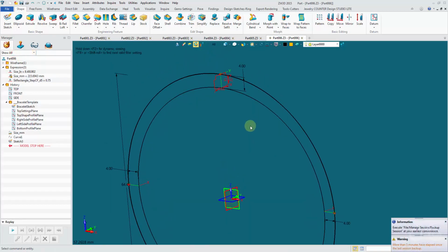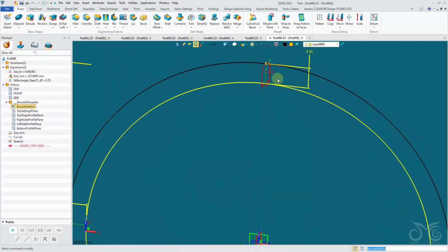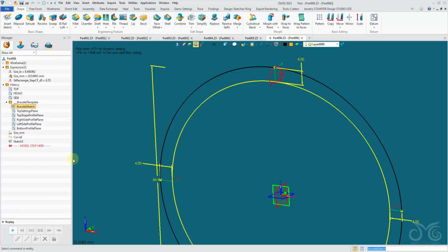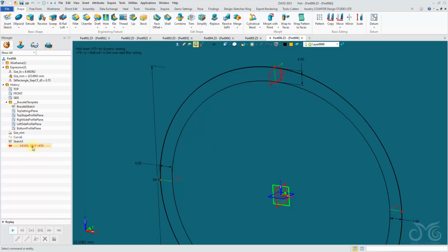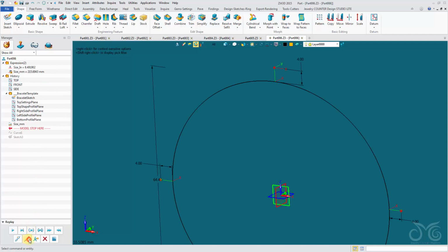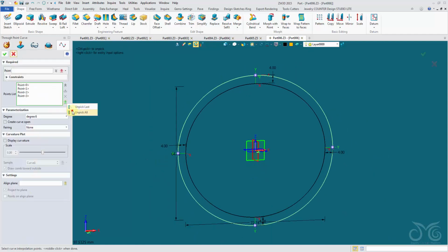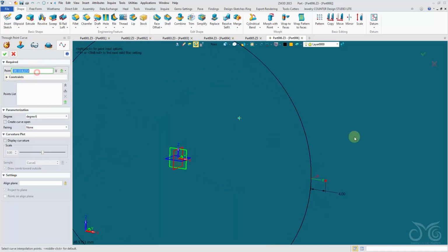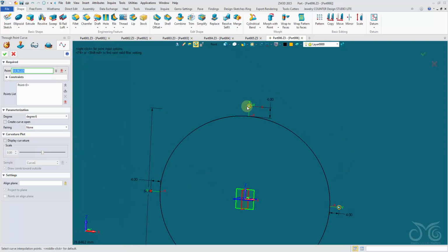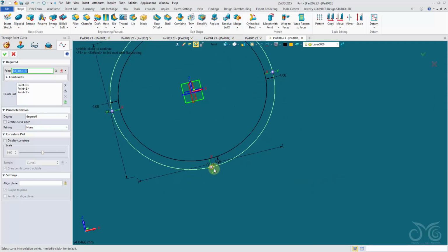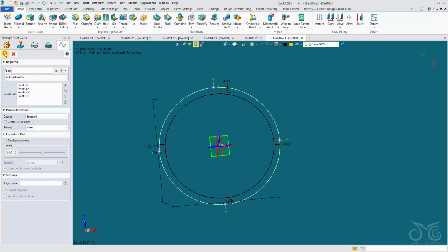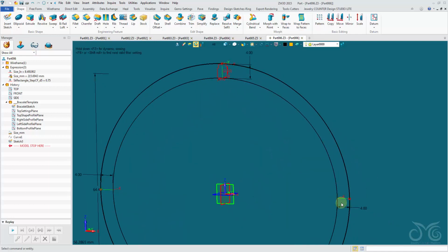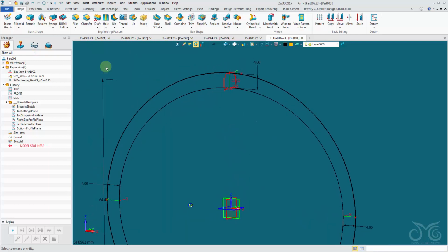To correct this, we could create a new curve on top of this sketch, with a starting point up here. Alternatively, we could come in and redefine this curve. I'm going to unpick all. If we want it to start at this side, this is where we begin our picking, so where we begin the curve. Confirm the operation. Okay, our sketch. I usually like to have it at the same point as our starting points, but it doesn't actually matter here.